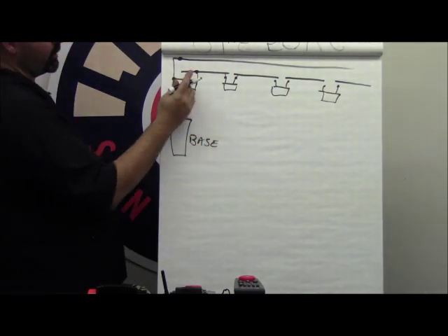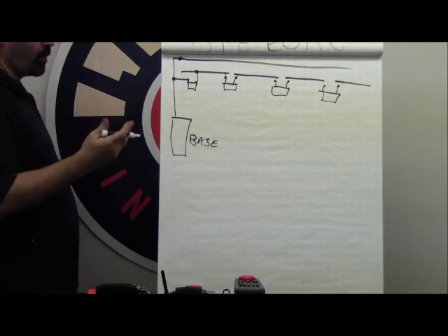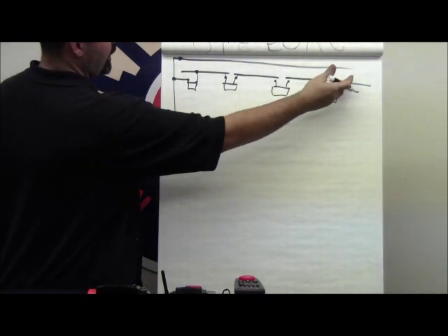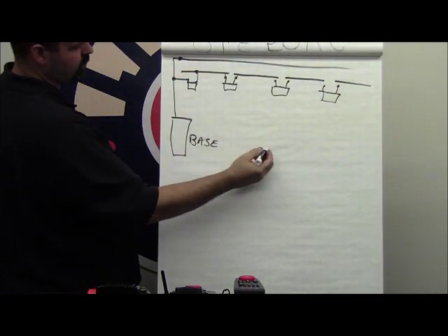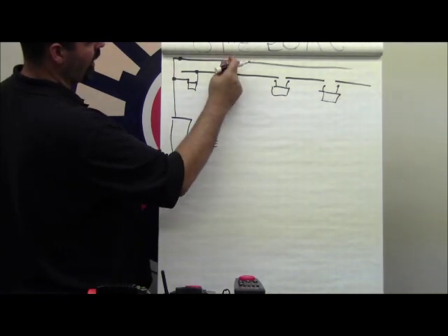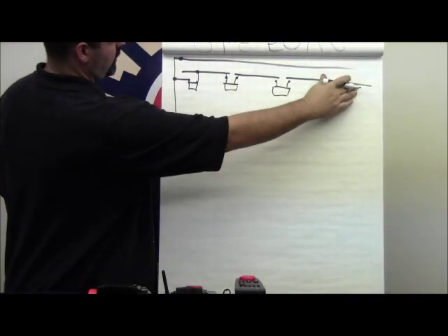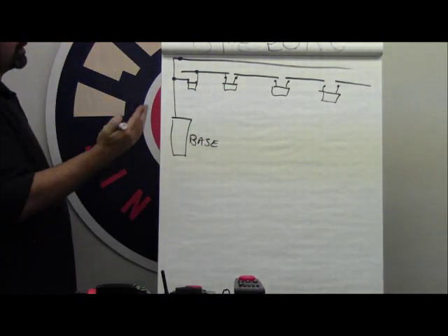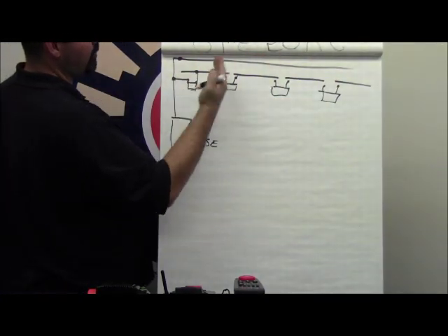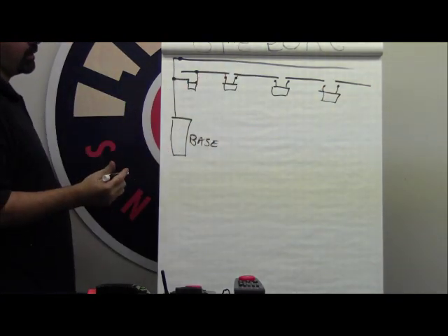And basically what you're doing is you're creating a capacitive coupling that allows the 455 kilohertz to broadcast over these electrically isolated rails so that you can still achieve the command signal broadcasting from both outside rails without actually putting any current through these rails or any polarity through these rails. So your wheels of your train will still continue to activate your block signals, but yet you'll still be able to transmit your command signal through both outside rails properly.